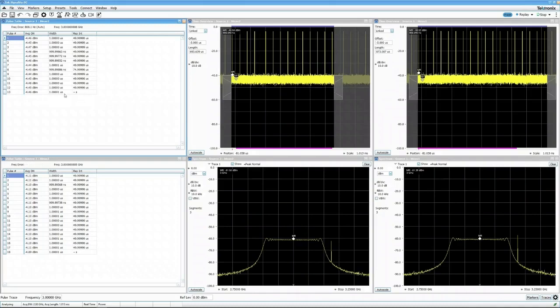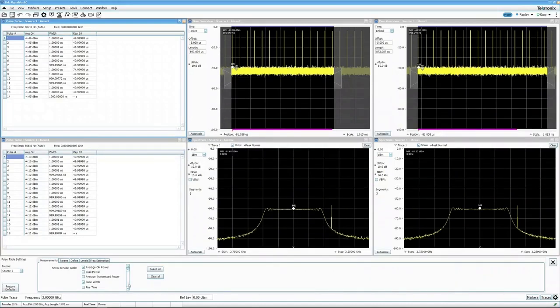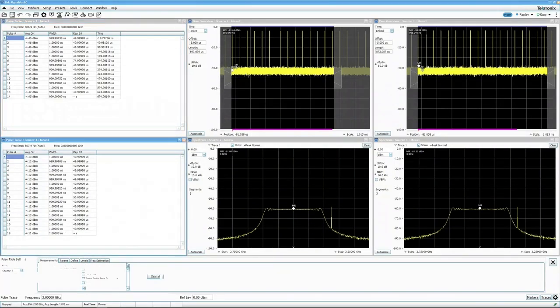The echo simulator ideally will not change the width or repetition interval. It applies delay, Doppler, and other clutter and channel effects before handing it back to the radar. Let us understand if it is applying any delay or not. To understand that behavior, let us turn on time measurements.